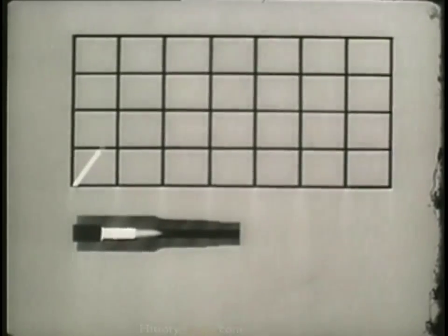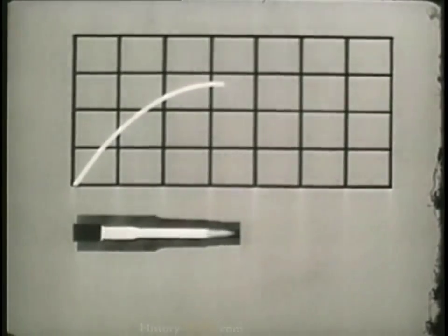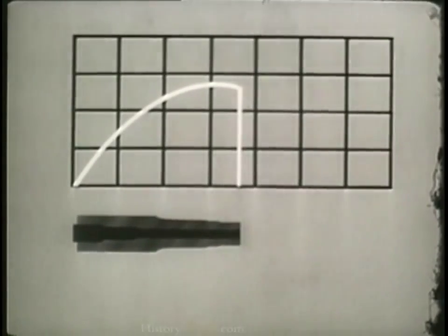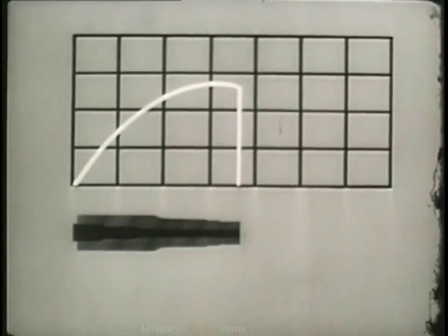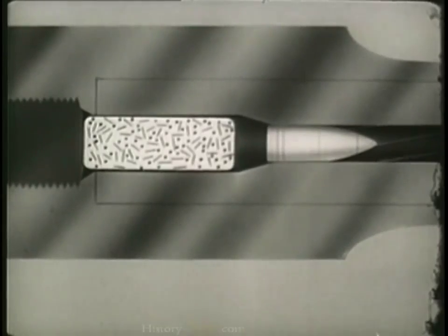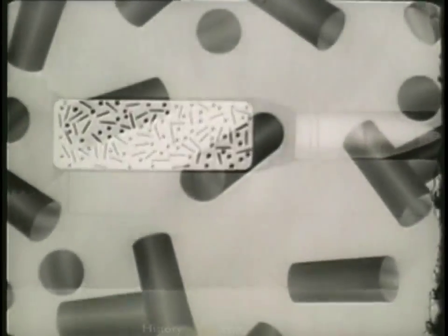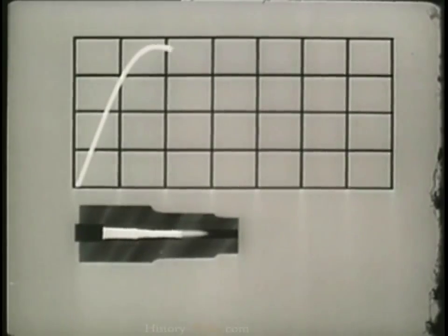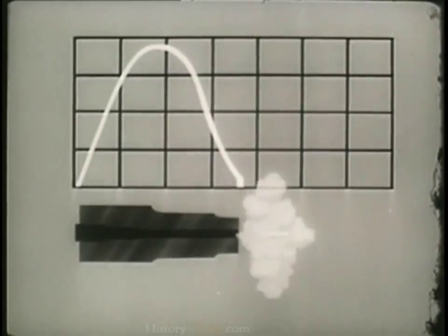There's considerable muzzle flash, and the powder continues burning even after the projectile has left the bore, indicating that energy is being wasted. For a short-barreled weapon, a small digressive grain should be used. This builds up maximum pressure quickly to accelerate the projectile in a short space without undue burning afterward. This kind of pressure action is just what we want for low-velocity weapons, such as mortars or pistols.